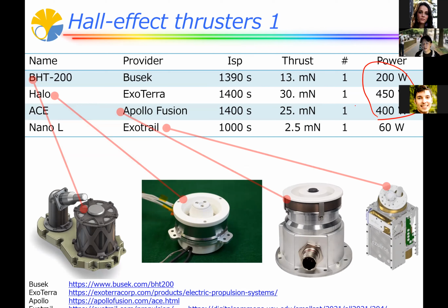It has very good performance in the high power range, and decreasing that power is somehow difficult. But recently, low power Hall effect thrusters are beginning to appear like this. And specific impulse, of course, this is electric propulsion, is much higher than the chemical ones, over 1,000 seconds. And the thrust level is in the 1 to 10 millinewton range.